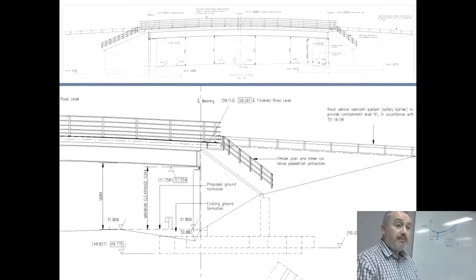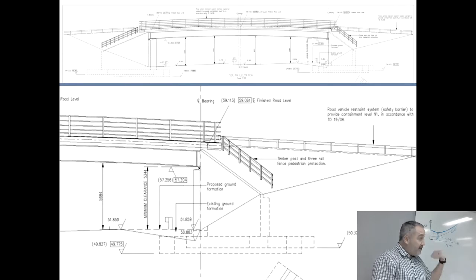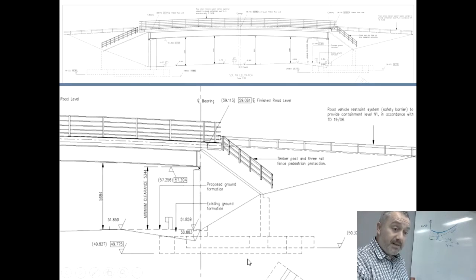In terms of the loading, you've got Eurocode 1 to look at the loading for traffic. You've also got the highways design. You've got the dead load of the actual bridge itself, so the steel and the concrete. You've also got the weight of the embankment all resting upon the abutments, which is transferred into the bearing capacity of the ground. You've got the weight of all the traffic, largely represented by a UDL for cars. Imagine that it's just full of cars.